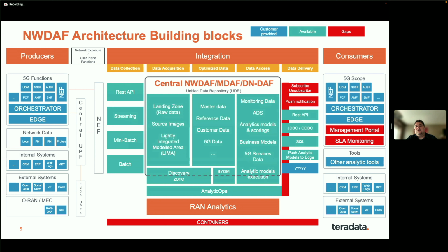There are some cases where we need to react fast and do inferencing of our models, and this is where we need streaming. And this is quite important because sometimes, especially in private networks, we cannot wait for the system to process the data. We need to have sub-second SLAs. And if you look at the industrial world, a lot of PLCs, which are those small enterprise edge processors, their processing loops are operating in 150 milliseconds, which means that we need to be able to capture the data, make a decision, and push it back.